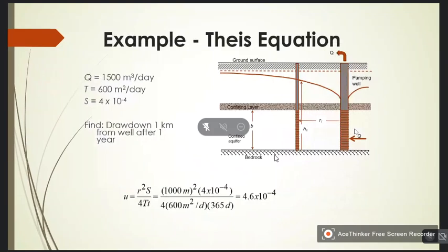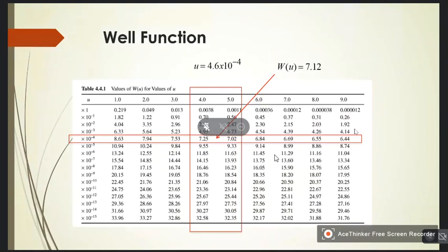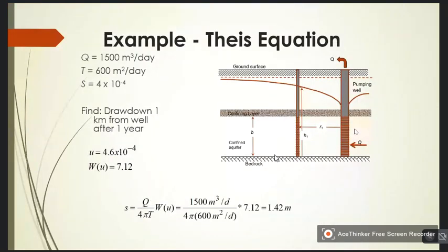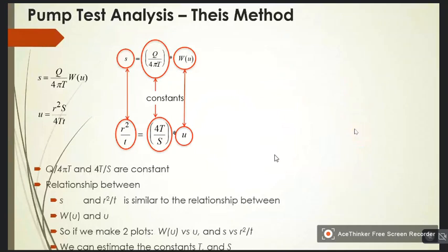And Theis's method of solution, using the well function table. Now, when we conduct the pumping test, analysis is done to determine the aquifer constants, that is storage coefficient and transmissivity coefficient. So for this, if you look at the pumping test,